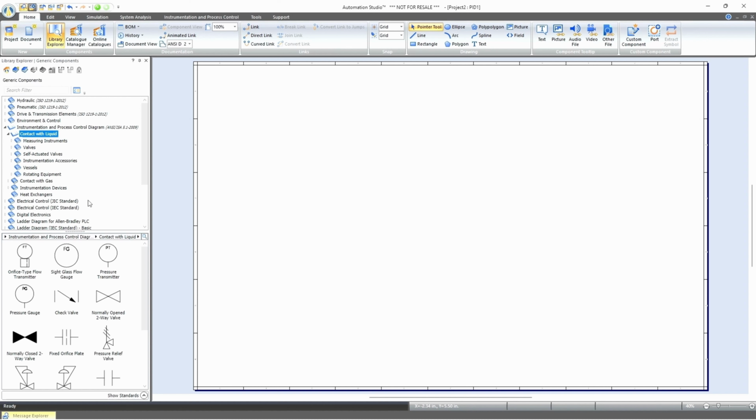So how to work with the P&ID? It's the same as any other technology: you would have components from the specific library. Small distinction: because the symbols are very similar, we have decided to split this library into two main categories, liquid and gas. This is the way it works in the software, and it is one of the current limitations, at least for the time being.